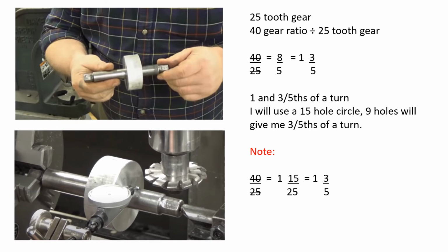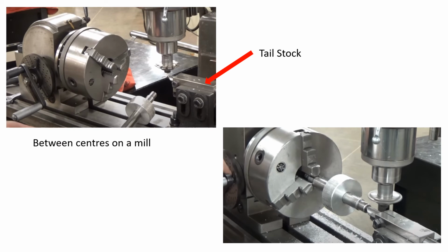There is a number of ways to derive the fraction. Use a system that you're comfortable with and confident with. As you can see, the dividing head has a matching tailstock. The actual center height can be adjusted with the tailstock. On the bottom right hand corner of the slide, we can see that the module cutter or gear tooth cutter is mounted in the vertical spindle.